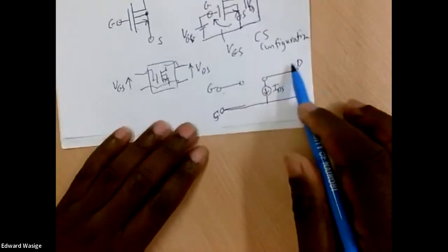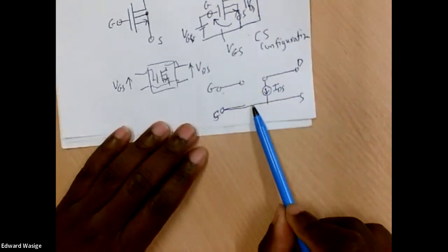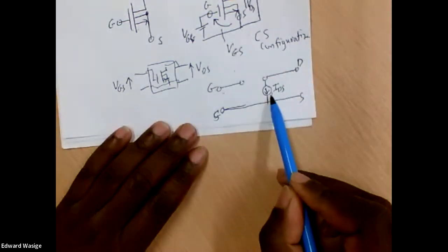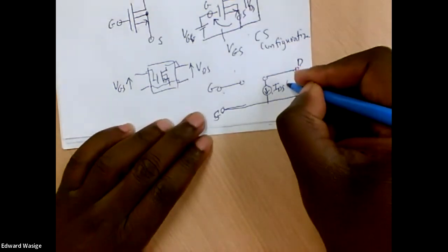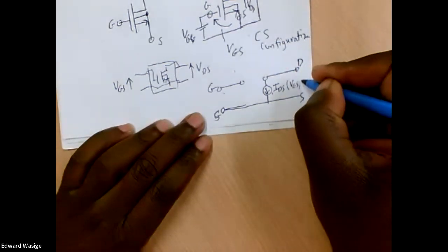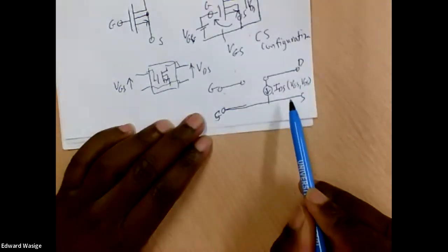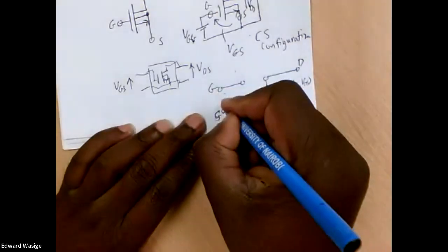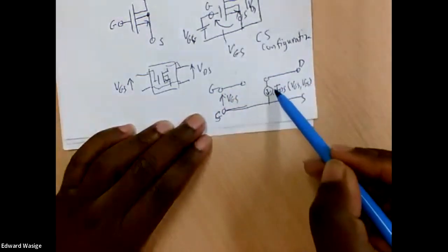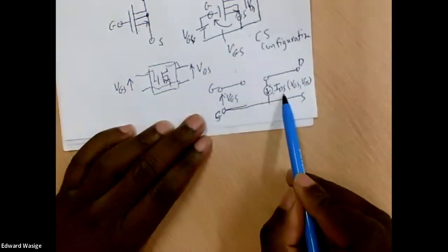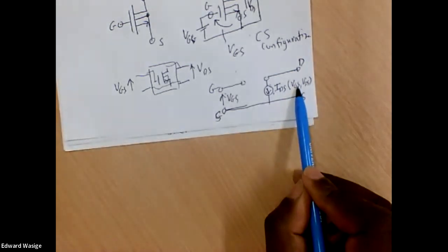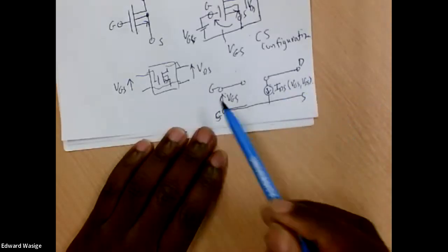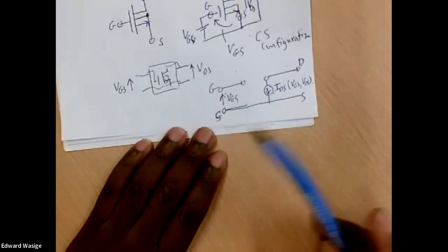So the first model for the transistor, we can represent it as a two-port network where we have IDS, and IDS depends on VGS. It depends a little bit on VDS, but it mainly depends on VGS. The current flowing between drain and source depends mainly on VGS, and a little bit on VDS, especially in the linear region, before the knee voltage, before it flattens out.